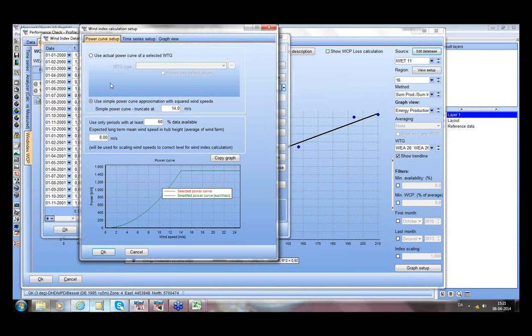The idea is that we would like our index to be relevant for the right spectrum of the power curve. If we use too high value, we will skew the data compared to the actual power curve, and the same thing if we use too low value. So let's take 7 as a guideline value, and we only use months where we have the majority of the data.